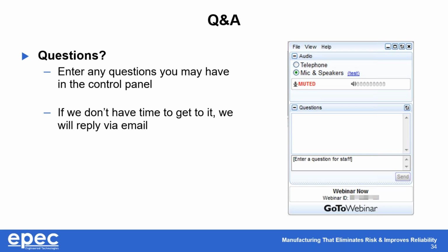What we do in the majority of cases at the prototype stage, as part of one order, we'll supply parts with and without shielding films under one part number and under only one tooling charge. That'll give our customers the opportunity to evaluate the designs both with and without the shieldings, and then make an informed decision moving forward into production as to whether or not shielding is specifically required for their design.